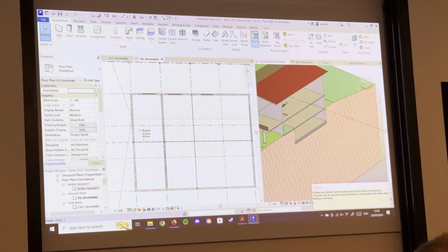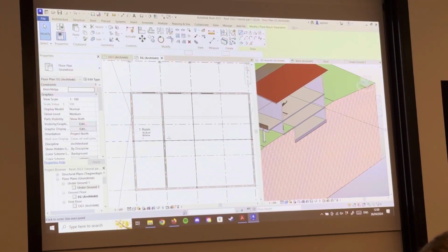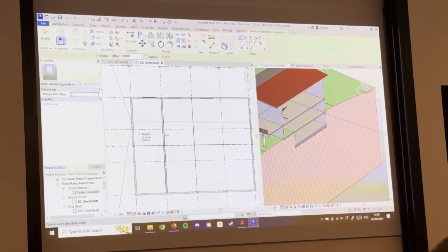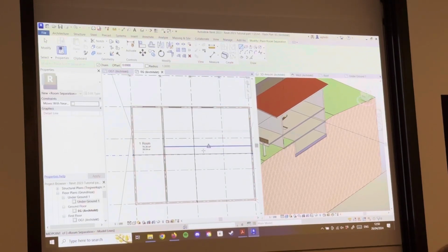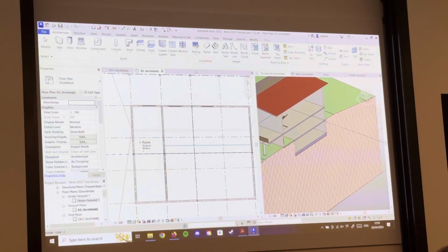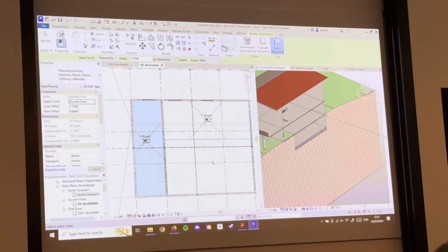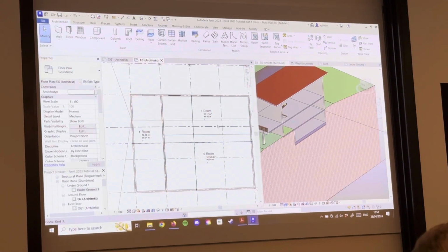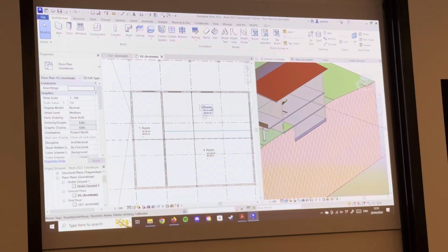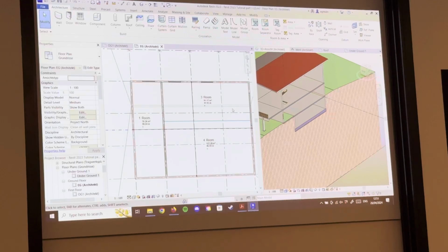What is worth mentioning is also the room separator that is just close to room. If you click on it and you draw a line wherever you want to separate the room, now, as you saw earlier, we could place a room there. But in this case, if we go again and click on room, we can place two different rooms. Because sometimes maybe you have the living room and the kitchen connected, but there's no walls in it. If you want to have two different areas, you use the room separator, and you place the room.